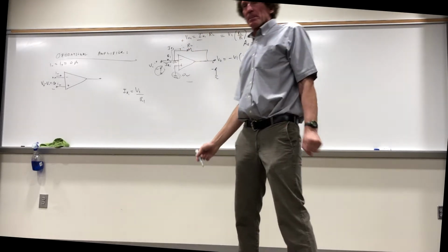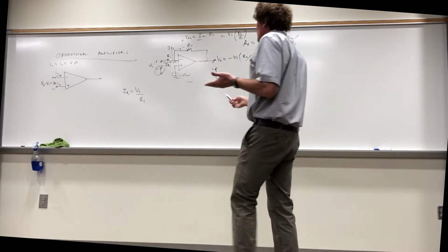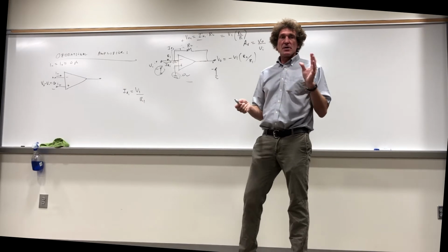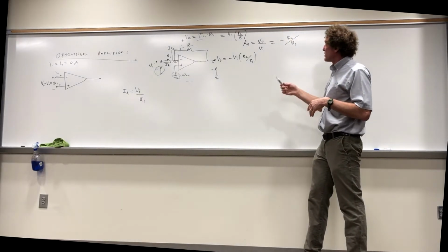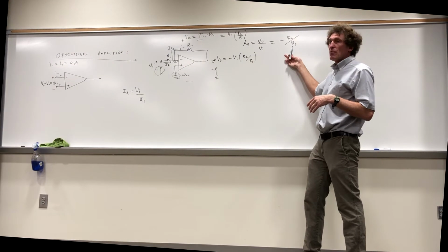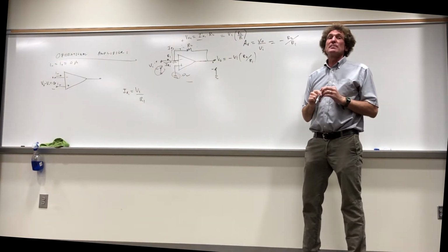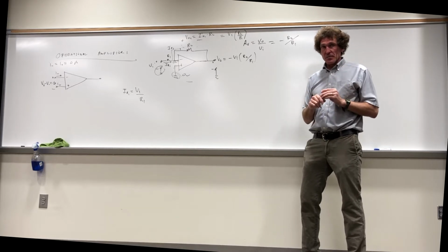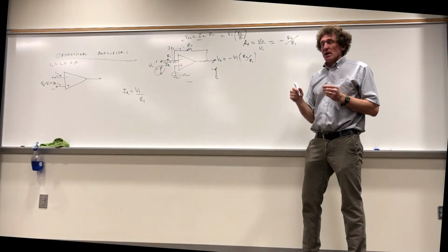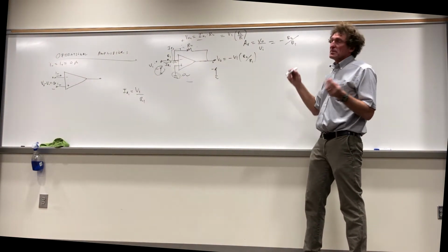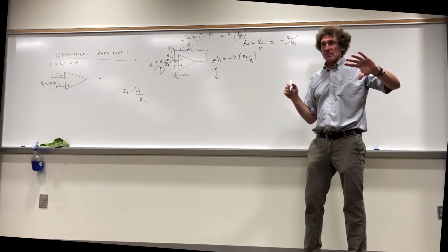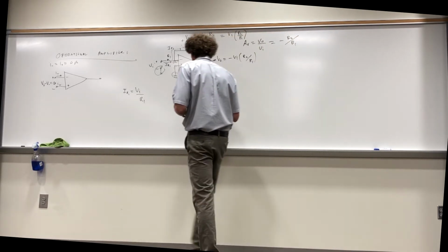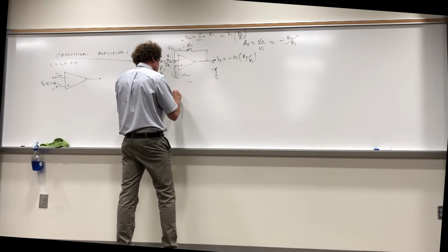It's a voltage drop. This is always called the inverting terminal. The input voltage polarity is inverted in the output. Now you can control the ratio of gain simply by the ratio of these resistors, R2 over R1. But it's always going to be negative. Got me on this? Now, something else I have to show you. This is general. We could use this if we wanted to get a simple amplification, but we get a negative factor in there. So one thing we can do is take this same circuit, and this is called an inverter,